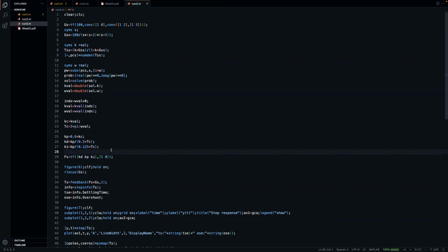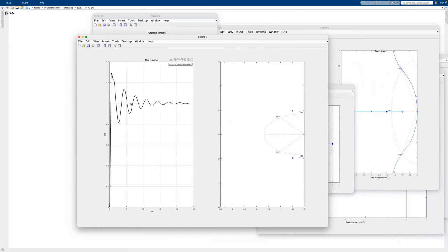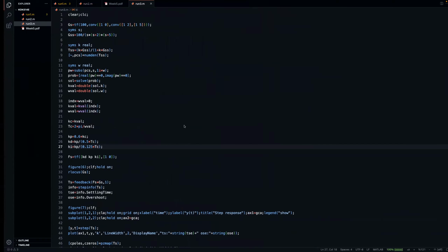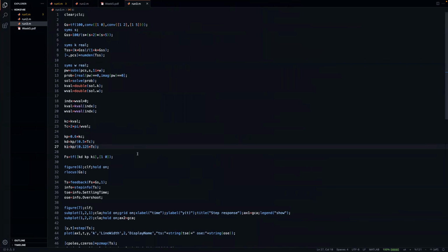And if you think about it, if you have a nonlinear system, or if you have an optimization tool and you want to start with a certain PID parameter set, this is the best strategy to start with, because it gives you a PID response that has stability and a certain performance. And then you might want to try to optimize starting with this response, for example. So that's why we should probably use it.